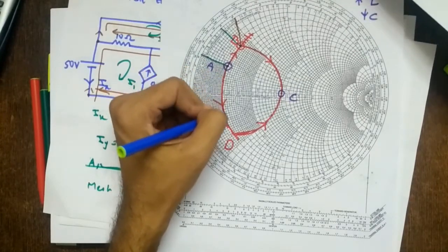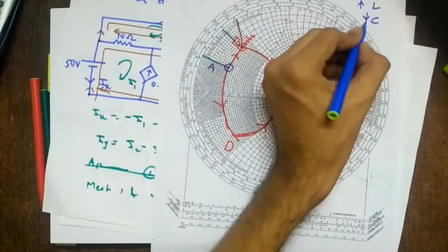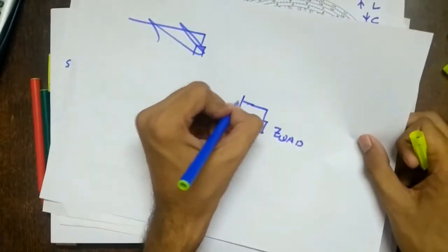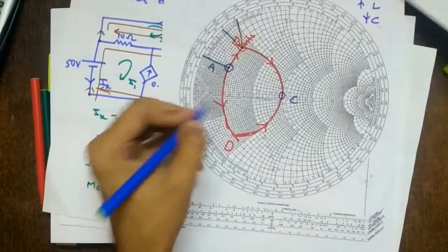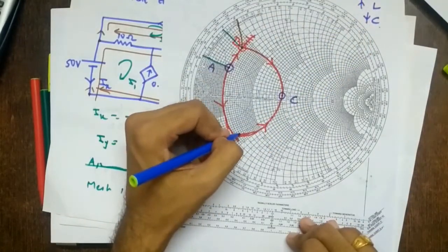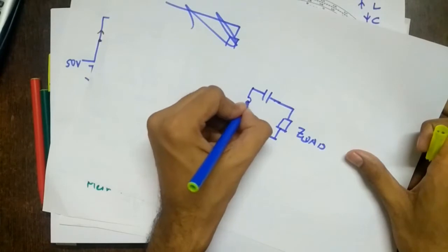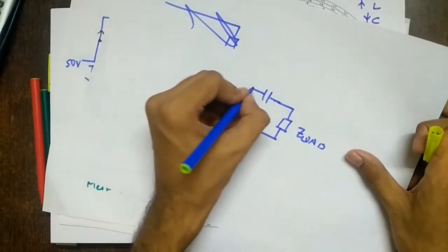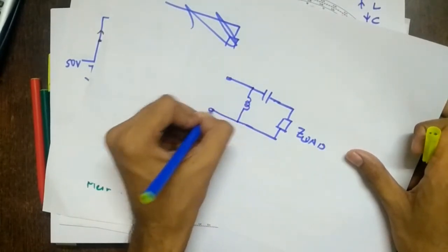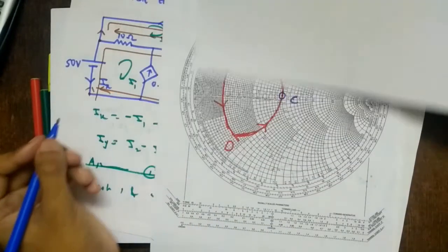We have moved along the solid line, the constant resistance circle. So it is in series, and we are moving downwards, so a capacitor. A series capacitor. Next we should obviously get an inductor. Let's check. We are moving upwards, so we are getting an inductor, and along the dotted line, so it is parallel. I told you if one is in series, the next will be the other element in parallel. So we have to find this L and this C now, and obviously the values will change.